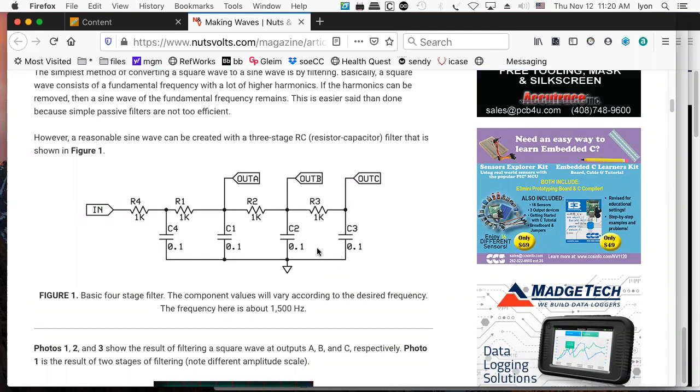So this would make a sharp dip, right? Well, the problem is that the sharper the dip you get, the more distortion you get at the knee of the filter. So if you were to build a filter that essentially just took out 19 kilohertz, which is very typical for FM radio because 38 kilohertz is the multiplexing tone between the left and right channels, you try and take out the 19 kilohertz pilot tone so that people don't hear it. That notch filter has to cause a distortion if all you want to do is take out 19 kilohertz and not 19.1 kilohertz or 18.999 kilohertz.